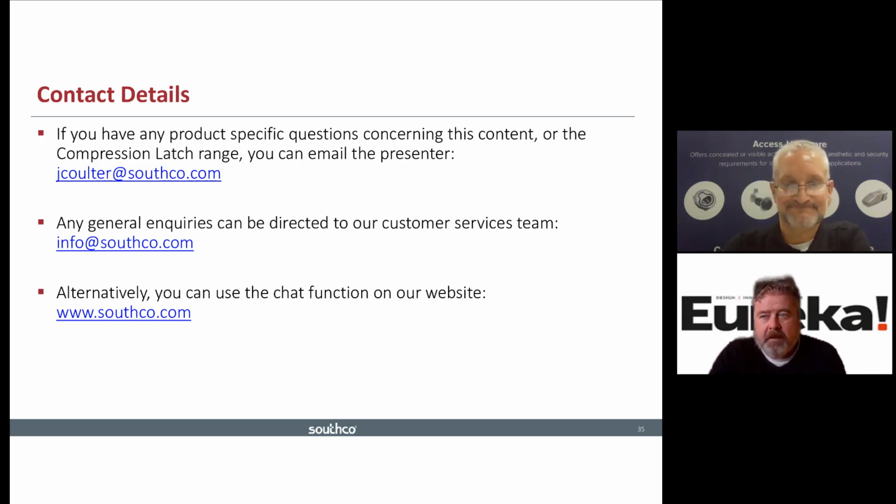Thank you. Next one. How do I determine what material I need for my application? Well, that also is a good question, Paul. A lot of that comes down to some of the criteria we discussed previously. For example, if your latch will be in an external environment where it'll be subject to wind and rain and harsh environmental conditions, you may want to choose a more sturdy material, such as a heavy metal like steel, or if you're in the application environment that sees salt water, you might want to use stainless steel, which is more resistant to corrosion.